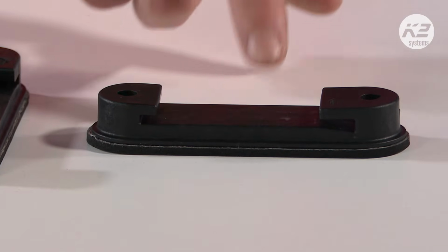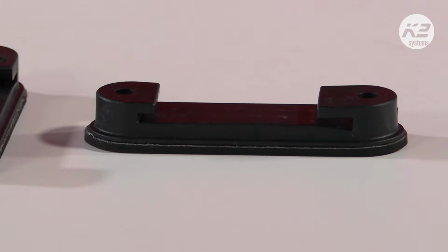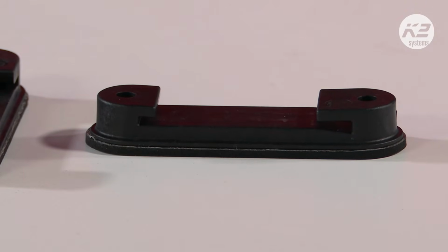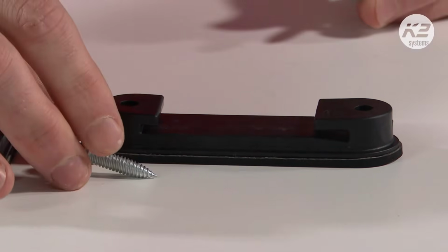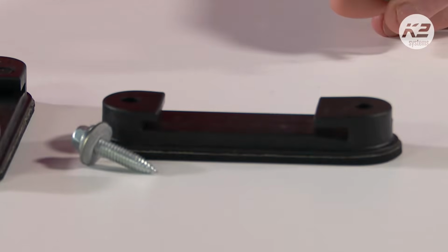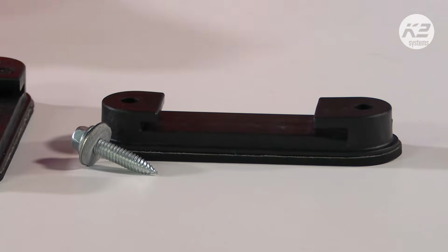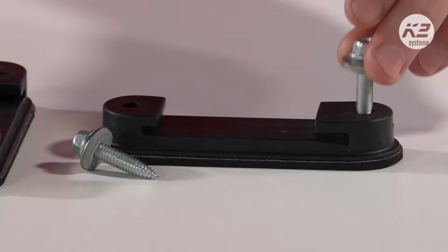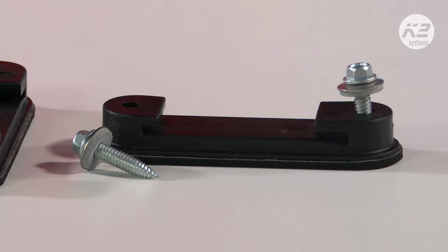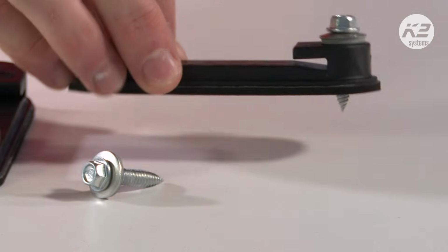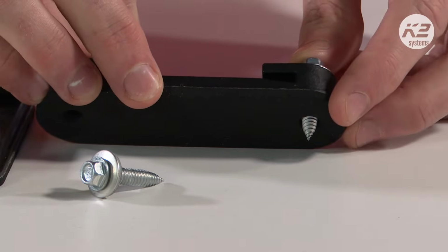And so these basic clips are fixed into the roof sheeting of the trapezoidal roofing with just some screws. These are special thread forming screws which will just sit in the basic clip, and then go through into the underlying sheet.